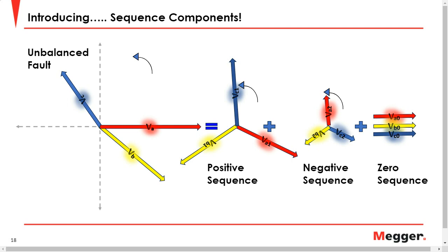So for a triple harmonic, and I'm only going with 3, but you could do the same for 6, 9, really any harmonic with an order of 3, you come up with the same math: phases A, B, and C are in phase.